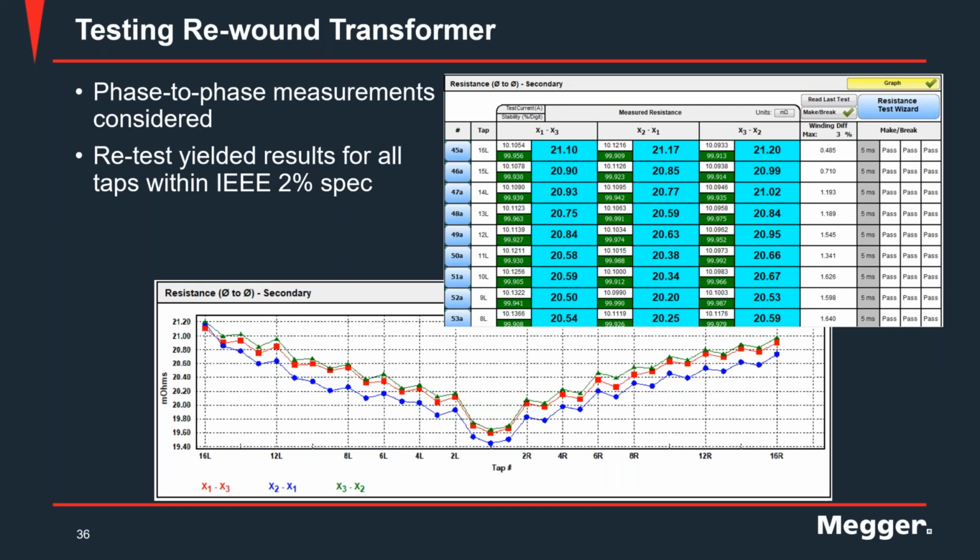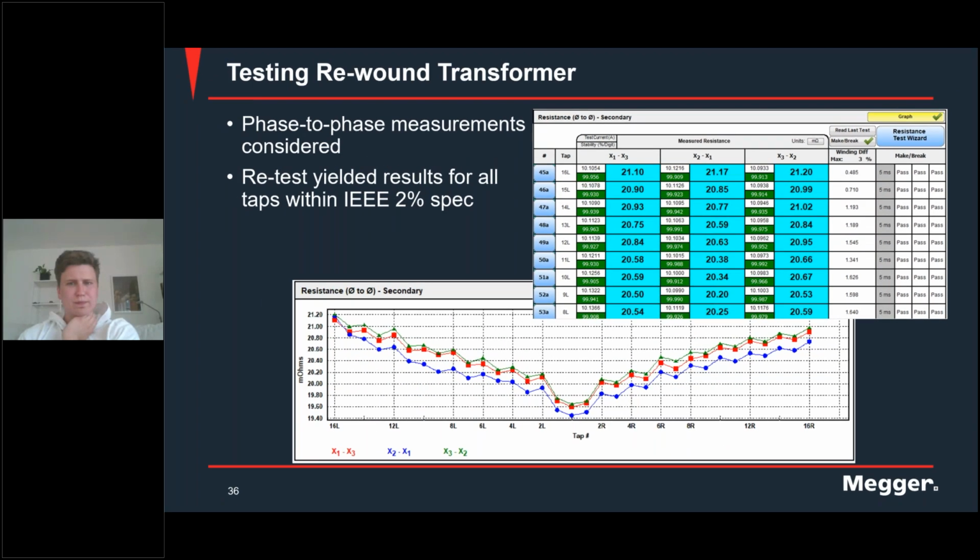Do nonlinear resistors have an impact on measurement? Okay, like a non-linear resistor, then I think about a diode or something. But in some sense, all the resistors are non-linear because they're temperature dependent. But if we look in a power transformer, I can imagine that you can have some type of non-linear contact problem if you have some type of burnt contact.